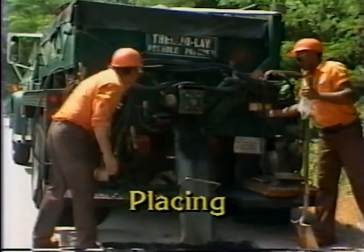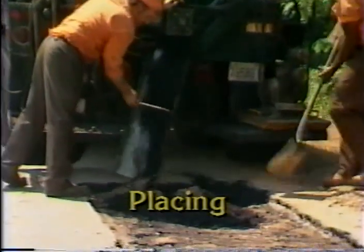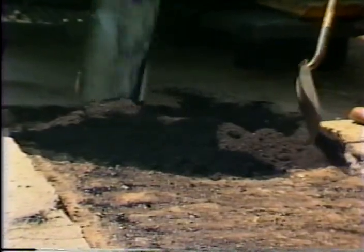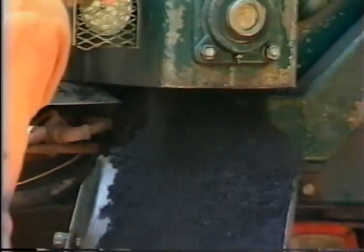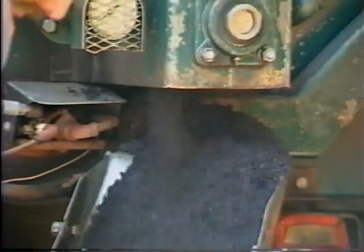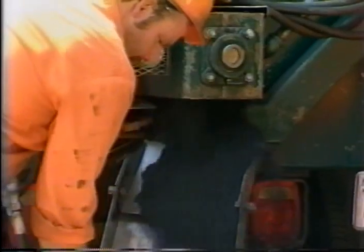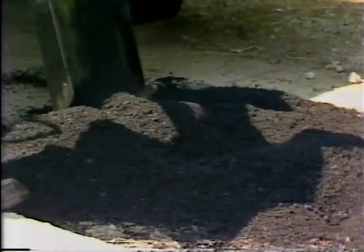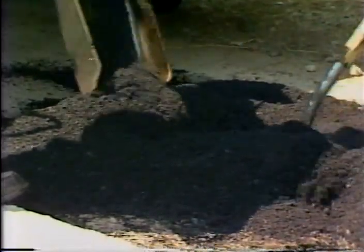The fifth step in the patching procedure is placing of the patch material. Placing is the action of filling the cleaned and tacked hole with patch material. A dense graded hot mix asphalt is preferred for pothole patching. It may be necessary to use a cold mix if hot plant mix is not available. Experience has shown the cold mix does not perform as well as hot mix.